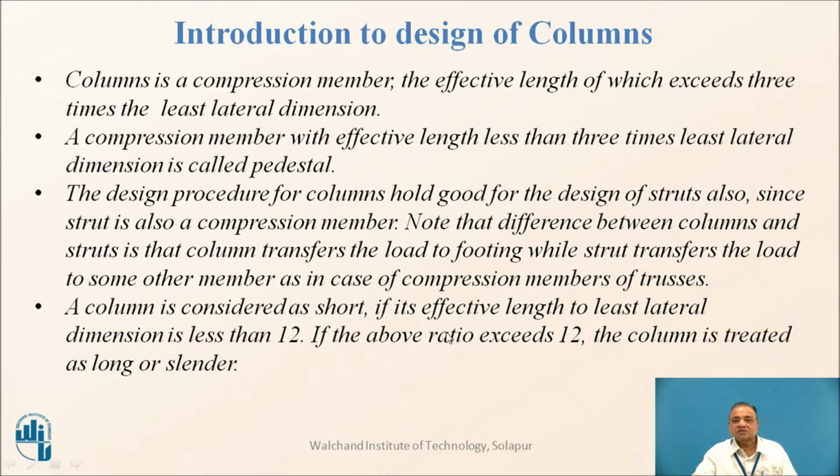The column is considered to be short if its effective length to least lateral dimension ratio is less than 12. If the above ratio exceeds 12, then it is treated as a long column or a slender column.